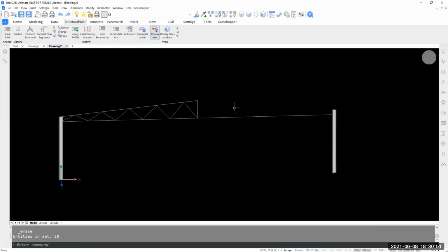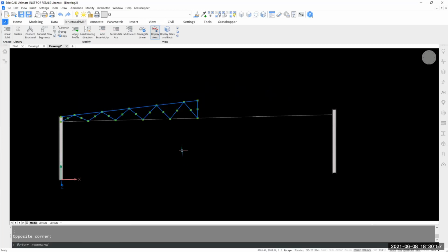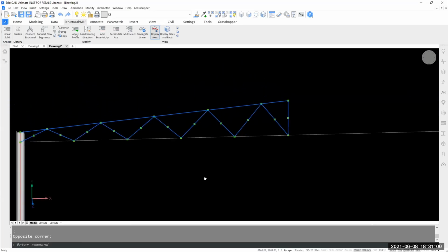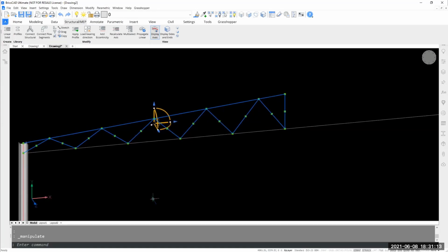And now we want to mirror this to the other side, actually copy and mirror it. So once we've selected all of those lines, again, a long left click brings up the manipulator, or you can access it from the quad. Now, generally, the manipulator will pop up in the middle of where you're working. You can very easily move the manipulator to what I think is a better orientation by grabbing that little white ball and placing it here along the bottom chord at the midpoint.